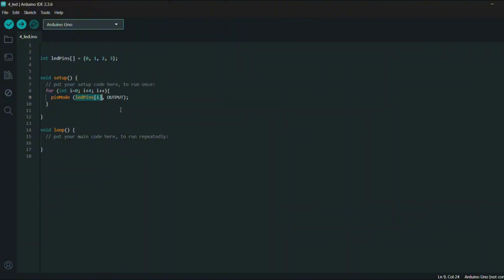That means this pin is made as an output, and it cannot accept any signal coming in, because those are digital pins that can act both as an input and output. So in this section, we have this statement telling the compiler that all those pins must be the output pins. So once we are done with this void setup, we now go into the loop.